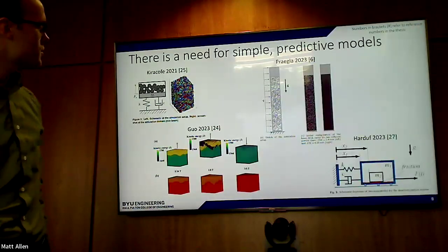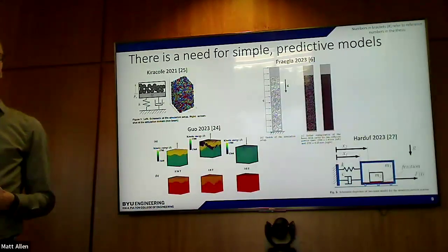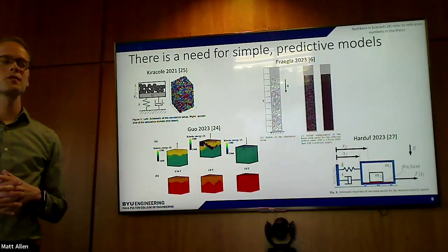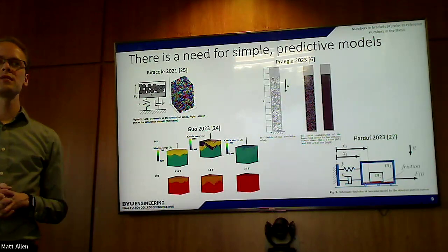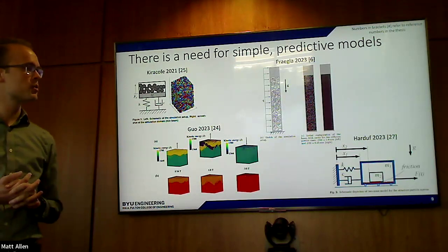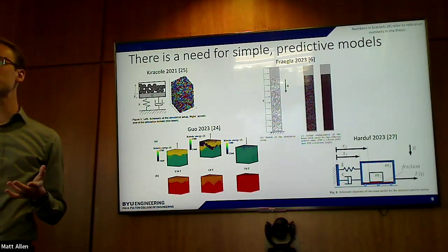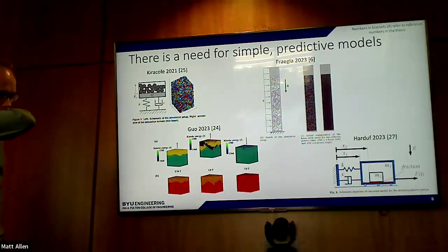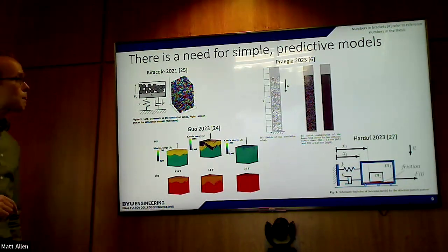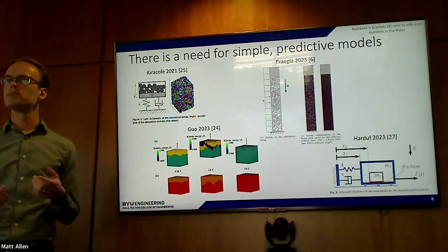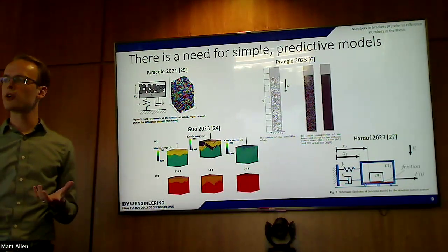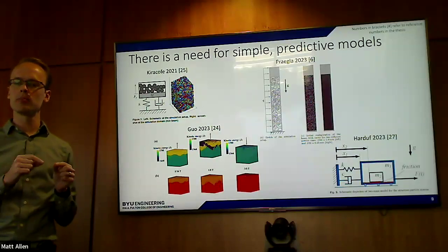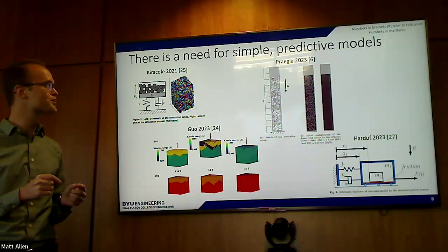So essentially, the behavior is really complicated and hard to predict, and what we want are models that can help designers to be able to predict how much damping my part is going to have if I put a pocket of these dimensions in this location. So your first thought about how to model trapped powder in a part like this might be, let's simulate all of the little particles of metal bouncing around.